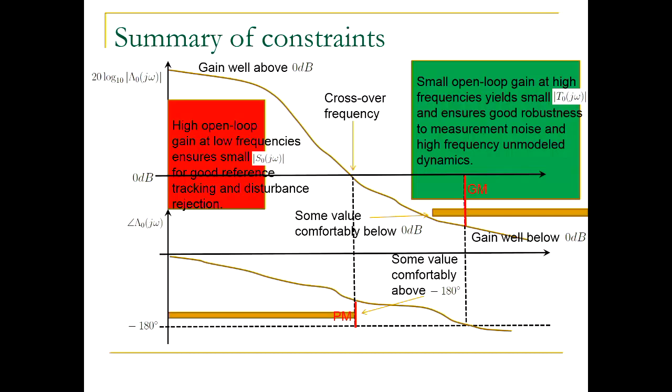So you see, any problem of compensation in frequency domain would require this step. This is the first step in any design. The first step is to translate a certain set of performance specifications into the constraints or the shape of the phase and gain plots of the open loop transfer function. Note here, we are talking about open loop transfer function, but we've already related how it affects all the sensitivities, right?